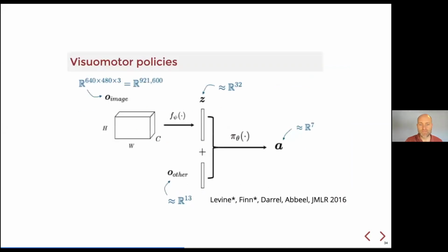So on to imitation learning. A lot of people are thinking about visuomotor feedback policies, right? Cameras, pixels to torques, if you will. Sergey and Chelsea were leaders in this area. If you look at the architectures of a lot of those systems, I was a little surprised when we started looking more carefully. They are relatively huge perception networks with relatively small policy networks right next to them. There's some big, possibly pre-trained network that is then being shoved down into a relatively low dimensional latent space. And then the policy itself brings in the state of the robot, for instance, and is a relatively small couple-layer multi-layer perceptron to do actions.